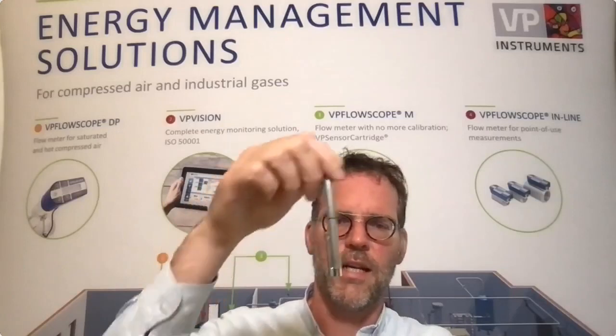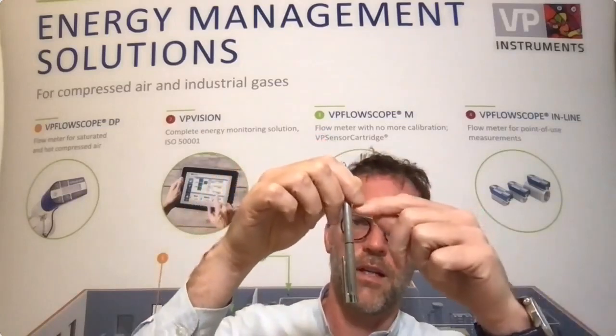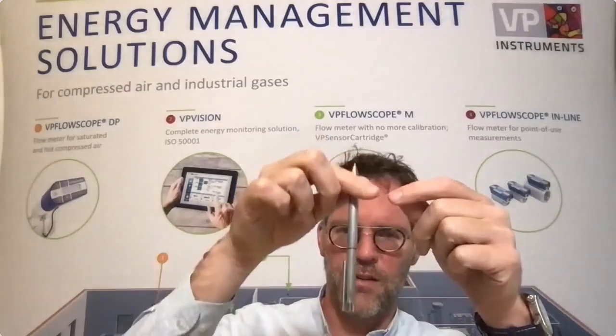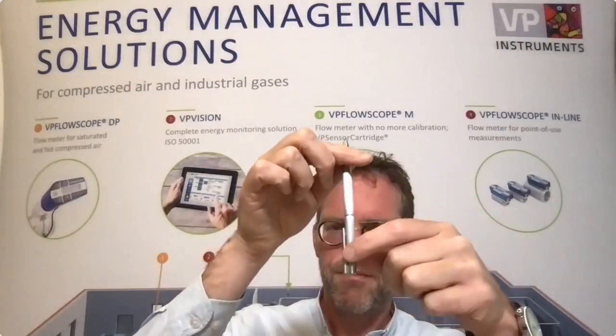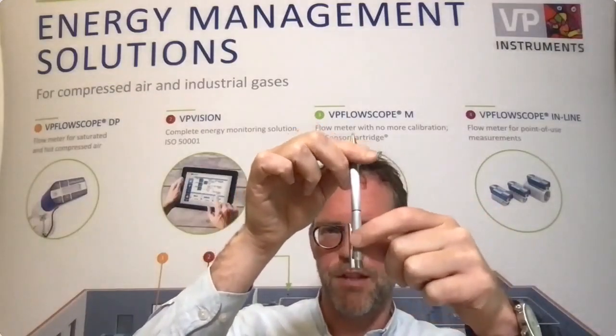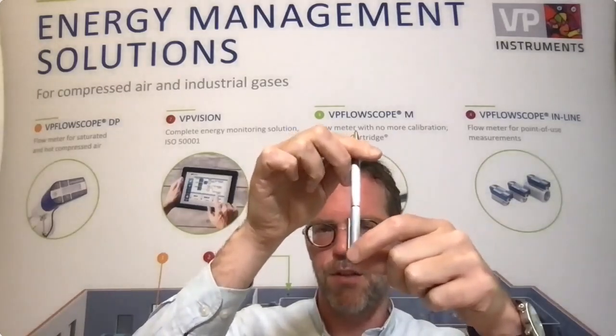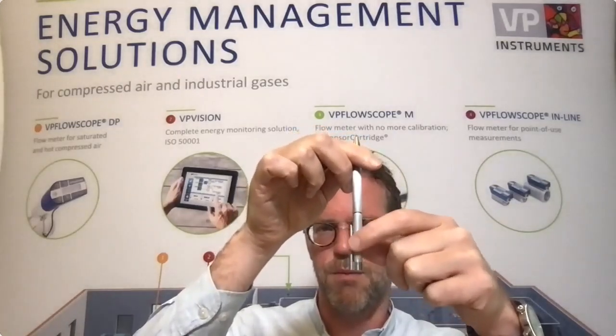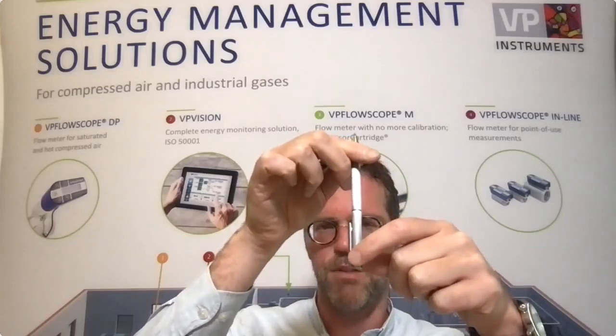The 30-degree angle installation, asked by Bernd Losberg. Why is it so important? I could try to illustrate it here with my pencil. If your probe is like this or like this, and there would be a drop of water on the probe, in this position it would drip down, and we have seen cases where the drop would come in front of the thermal flow sensor, or in front of the pitot tube differential pressure sensor.